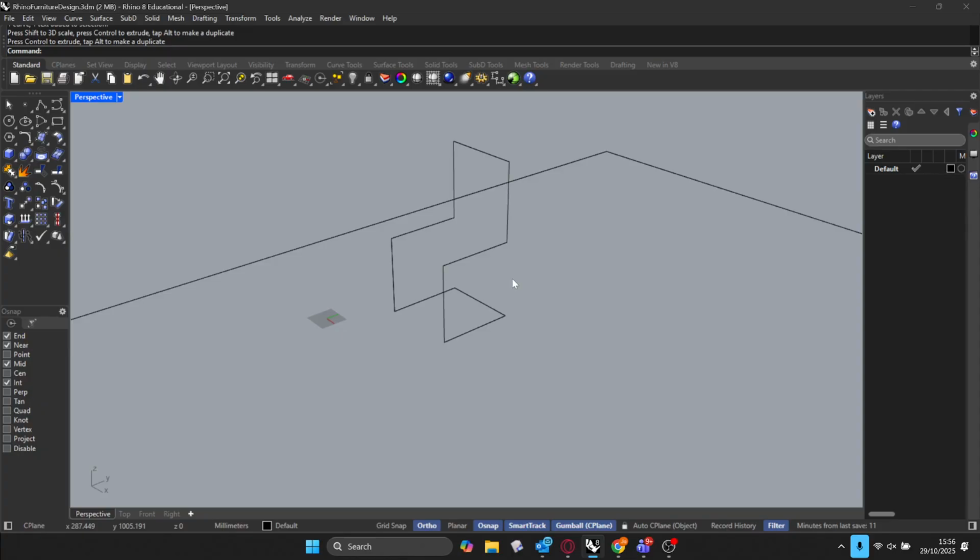Okay? Has everybody gotten to this point? Has anybody not gotten to this point? You're almost there? Okay, so there's a couple of commands that we're using. We're only using copy, move, and rotate. They're the three commands that we've been using so far. And if we make sure that our object snaps are turned on, we'll object snap. And when we're rotating, if we turn the copy on in the menu bar, then in the command bar we know that we're rotating a copy. Everybody okay with this so far?